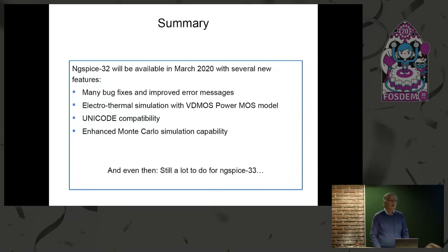Yes, there has been someone doing a translator that takes the Cadence Spectre input and translates it into the ngspice netlist. And the models, of course, you have to select. ngspice has a certain number of models available, and if these are the same as in Cadence, well, BSIM3 for older processes, BSIM4 for newer processes, then you can do that.